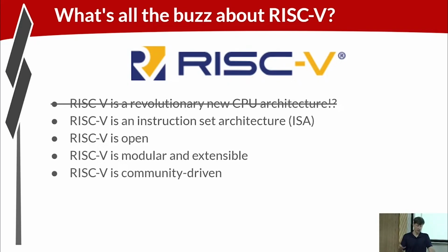So the M extension for integer multiply and divide. You can execute code without integer multiply and divide. How do you do an integer multiply and divide if you don't have an instruction for it? You do it in software using other instructions. If you need to do an integer multiply, but you don't have a native integer multiply instruction, you do some sort of a loop just like we did in grade school, learning long multiplication, right? That's going to perform that operation.